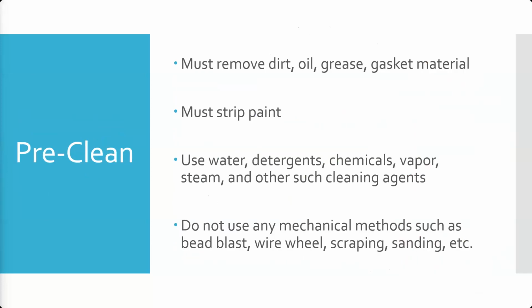When we're done, we probably want to clean it up. So pre-cleaning to remove any of that oil, grease, gasket material, dirt. Right? When you're doing engine stuff, gasket material is important to get off of those sealing surfaces. It's not an uncommon area to get cracks, particularly if you're doing automotive, right, around like head gaskets and things like that. Okay. By the way, if you are rebuilding a car, visible dye works really well to try to find coolant leaks and that kind of thing, internal coolant leaks when you're doing head gaskets and stuff.